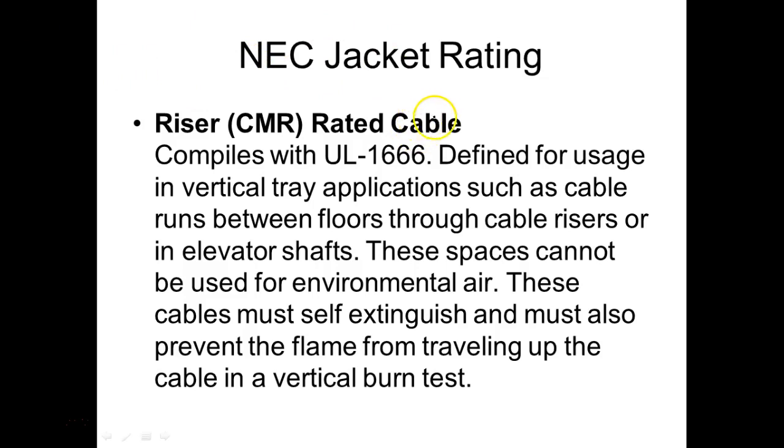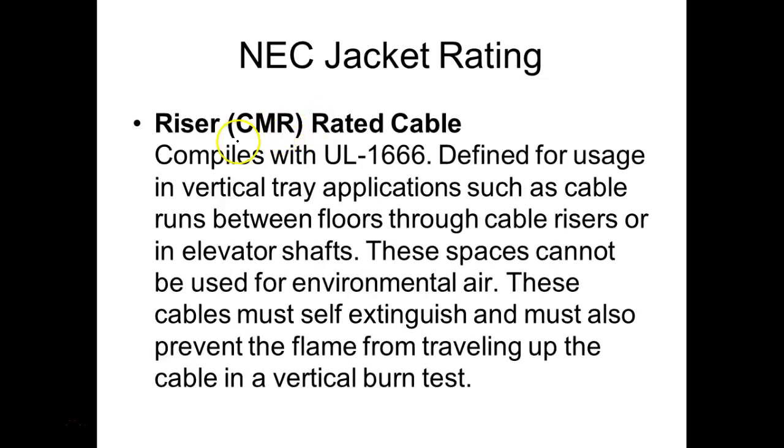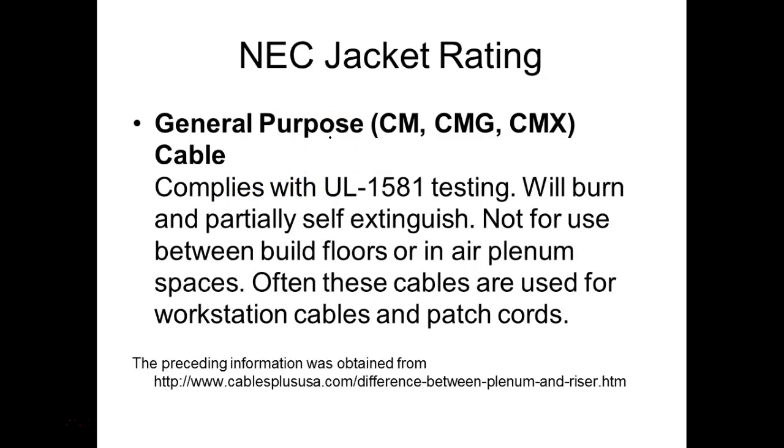So these are your riser cables. CM, these are your designators. R, riser. P, these are pretty straightforward. CMP, if that's on the outside jacket, that's going to be a plenum rated cable. CMR would be a riser rated cable.